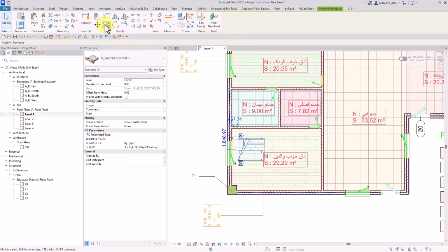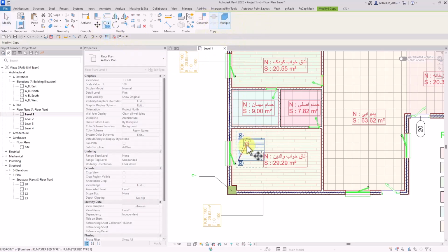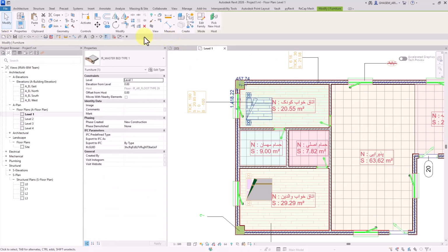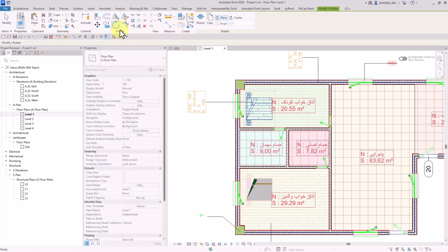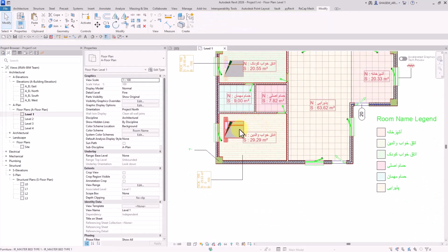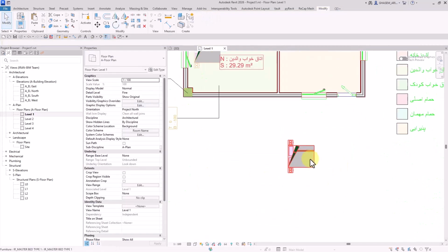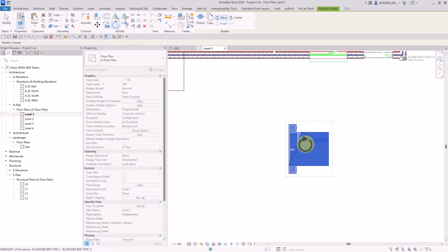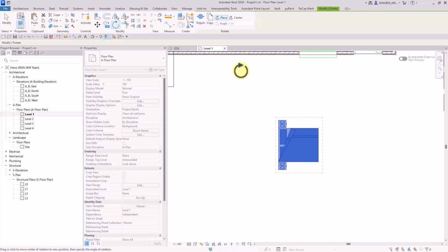The same goes for copy, or basically other modifying items such as rotate, which is actually one of the most interesting items and features that we have in this version of our software. Let me set this here. Previously, the midpoint of this bounding box automatically would have been selected as the rotation center point, but now we can use this placing item to specify the center point basically wherever we want.